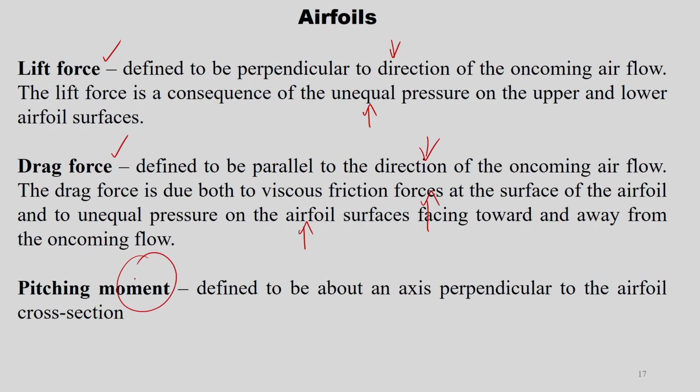Pitching moment is defined about an axis perpendicular to the airfoil cross section. If you have an airfoil like this, you would have the lift force in this direction and this would be your drag. So, pitching moment is nothing but this way, right. This is the pitching moment, which is about an axis perpendicular to the airfoil cross section.